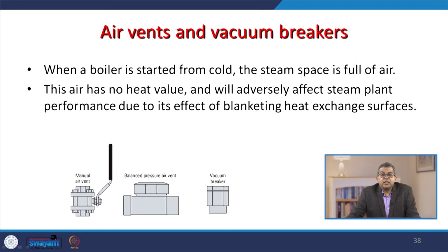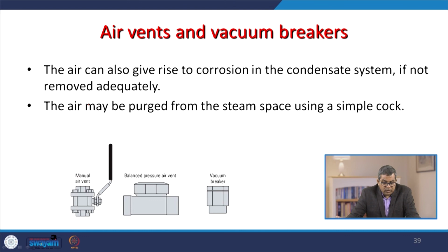So, it adversely affects the steam plant performance due to its effect of blanketing heat exchange surfaces. So, you need to remove this air, and this air can also give rise to corrosion in the condensate system if not removed adequately, and this air can be simply purged from the steam space using a simple cock.